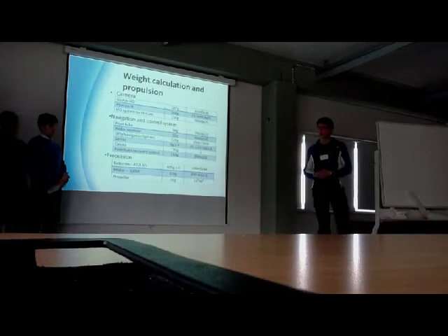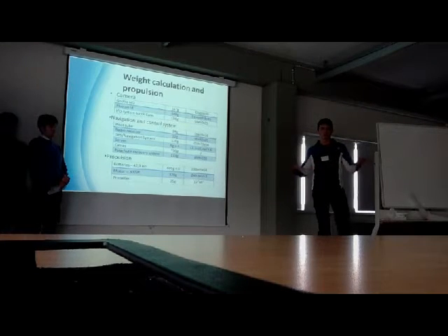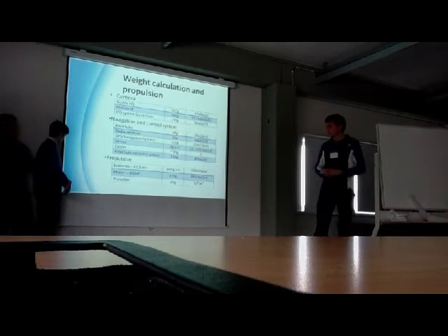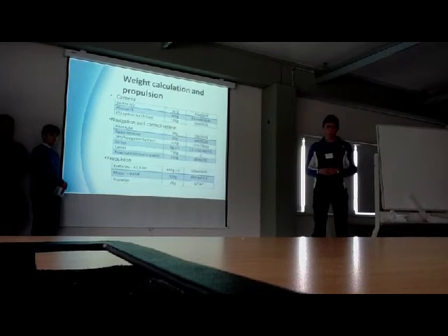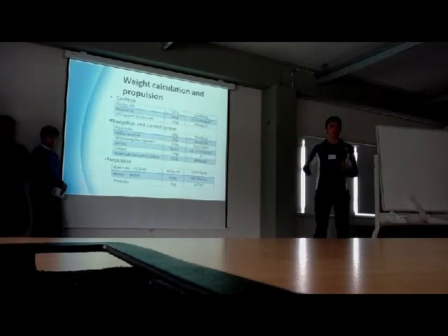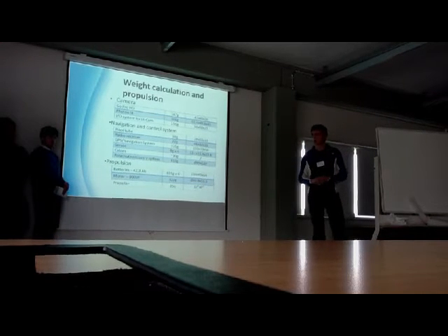We spent a lot of time searching maybe for solar cells, things like that, but it's not easy in our case because we don't have a big surface, less than 1 square meter, so we cannot get a lot of energy back. And finally, we chose to make the mission in 2 legs, because Ostend is situated more or less at the half of the Belgian coast. So we have the idea to make a first leg, for example, to the north, and going back we can change the battery and make the other movement. So we calculated the battery for 1 hour of flight.